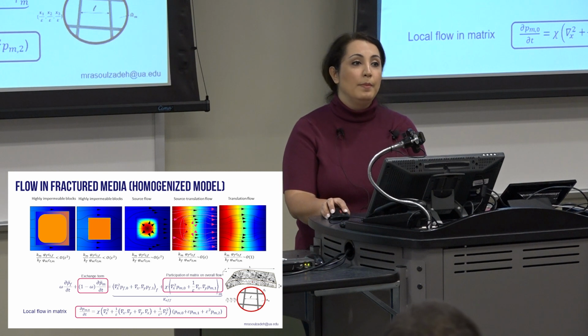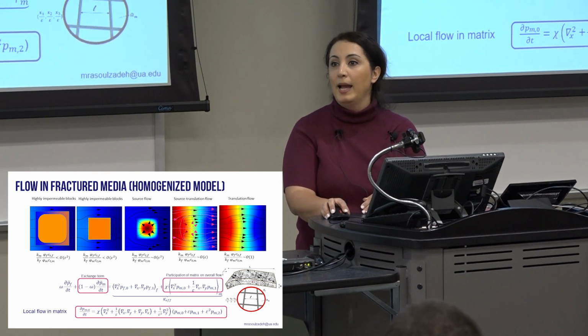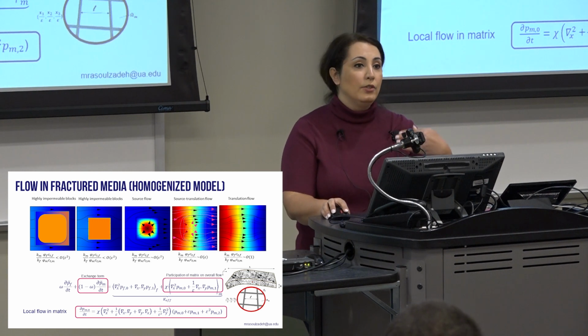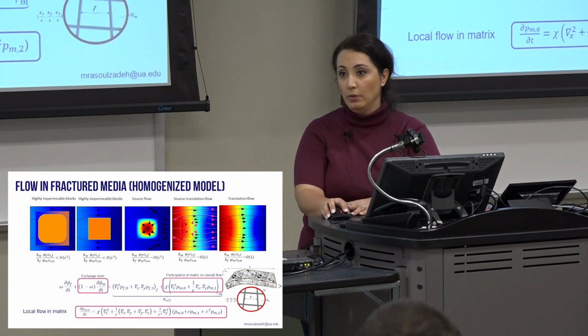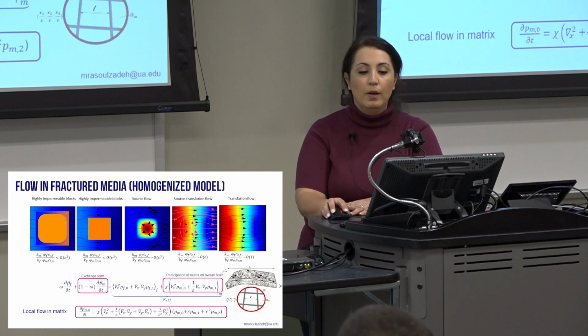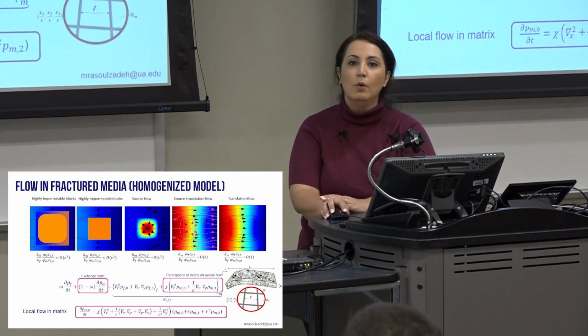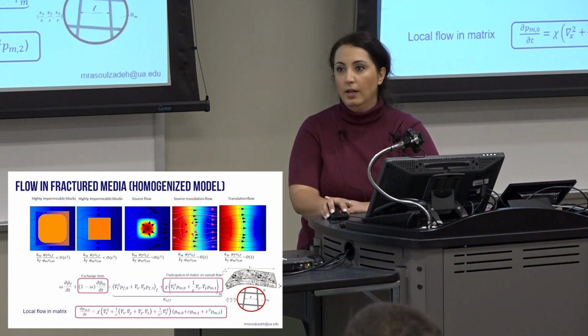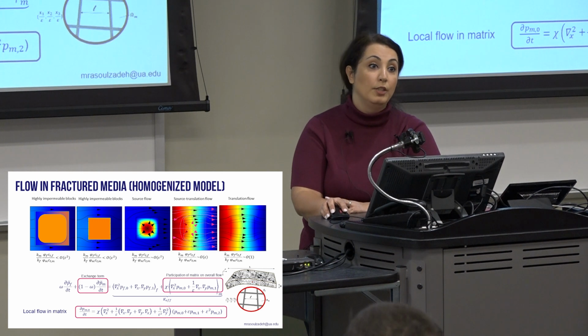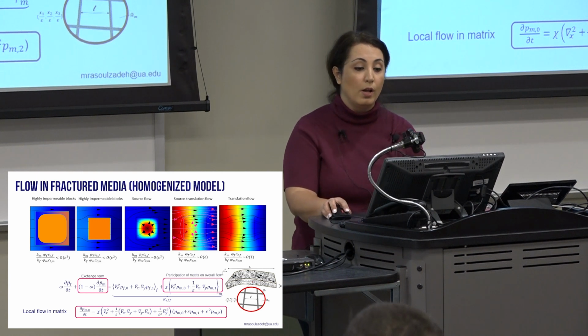if matrix permeability is close to the fracture permeability, the ratio is of order of magnitude 1. Basically, matrix participates in the flow as we expected. Some of the streamlines may slightly go toward the fracture because there is an easier pathway to go. But anyway, we will see the full contribution of matrix in the flow process.